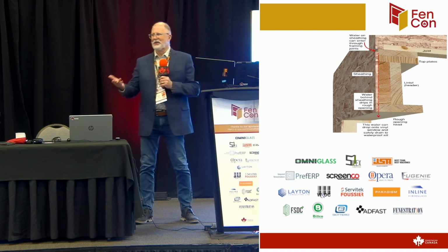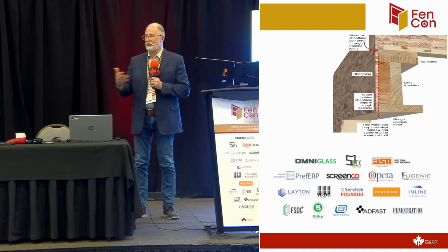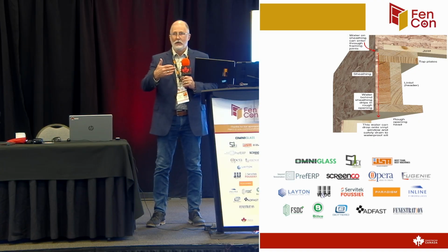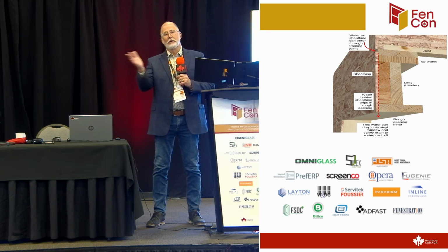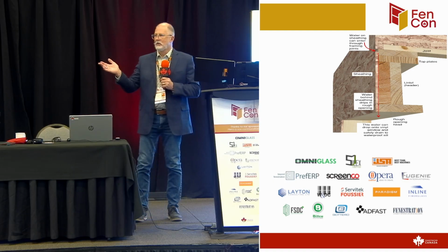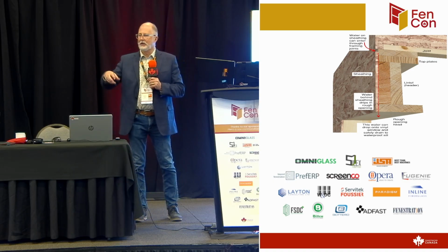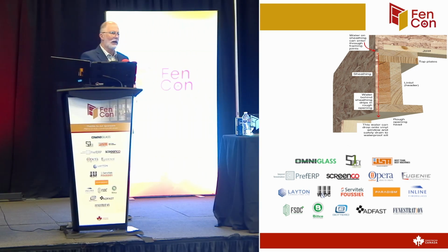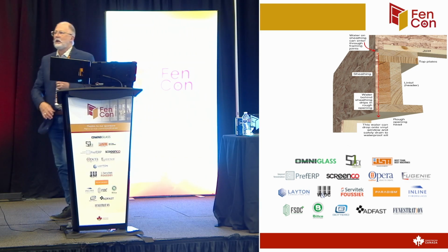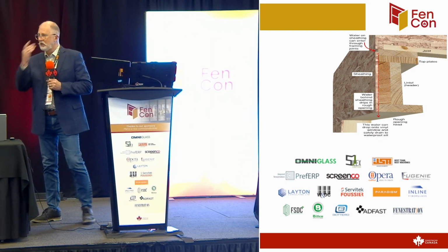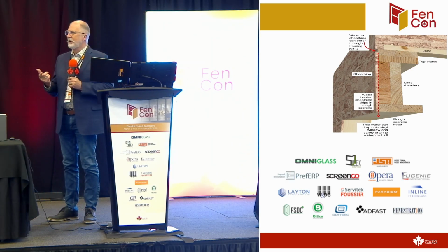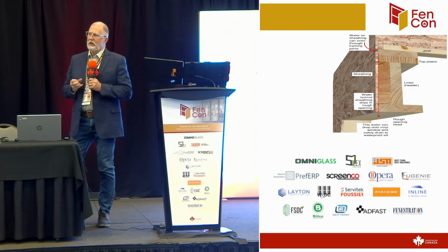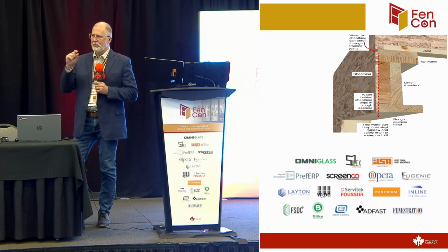Yeah. With better doors, doors have always been problematic. The other one that's problematic is outswing doors on decks, because the deadbolts, the openings, everything gets in there, and then guys will put their decking on after the fact, and everything drains behind the deck. That's problematic, but I think there's got to be a balance there. I don't see the need to have the space underneath. On the committee, I fought against that because I don't see the point of it. What's the purpose of the space at the bottom anyway?